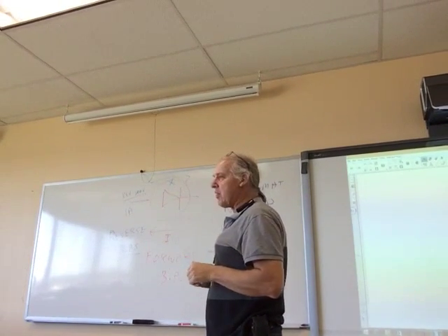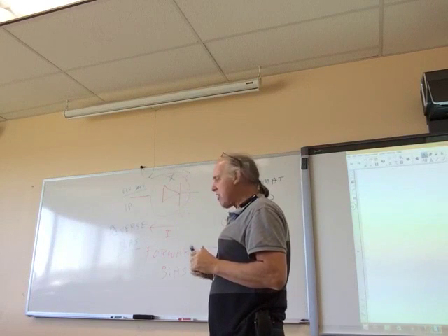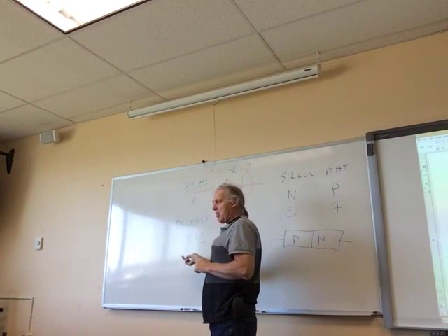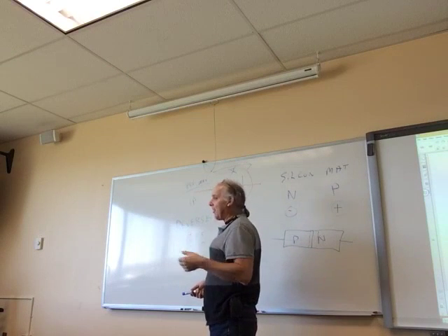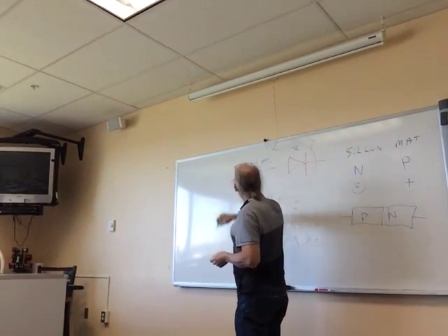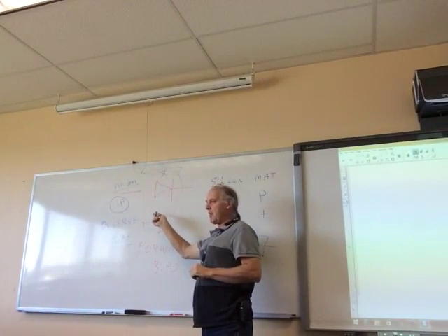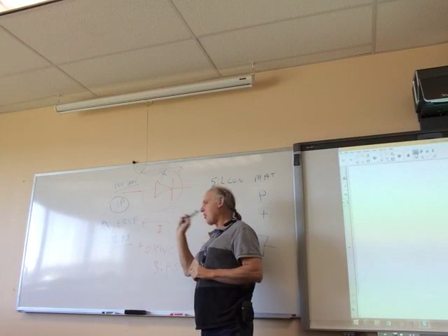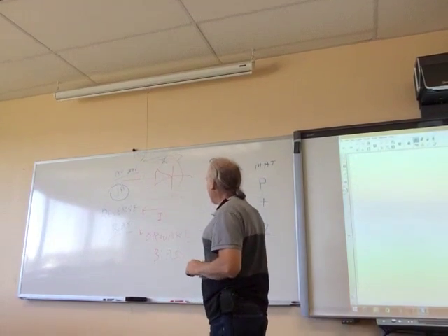So could I use 120 volts on this? Absolutely. Will not overcome the reverse bias. Now, if you overcome the reverse bias, it does what's called avalanche, and it burns up in a hurry, and I've actually seen pieces pop off and hit people in the forehead. So when they go, okay? So I got one that's 1 amp. So now I know that if I forward bias my diode, I'm going to be able to flow up to 1 amp. If I go over that, I'll burn the diode out, okay? It doesn't burn out quite as violently if you do it forward bias as it does if you do a reverse bias, okay? All right.